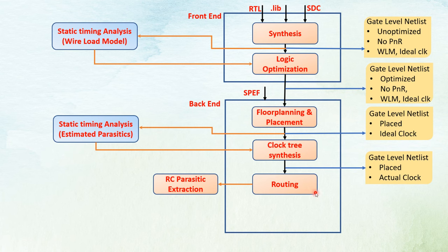Routing in VLSI is a process of making physical connections between the signal pins using metal layers. It has several goals, such as minimizing the wire length, delay, area, and vias; a proper via connection from one metal layer to another should be there. Also, it checks timing and checks that all the design rules specified by the tech LEF are properly met or not.